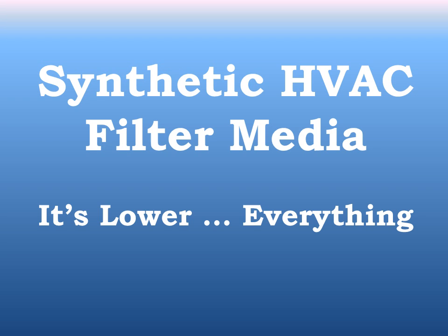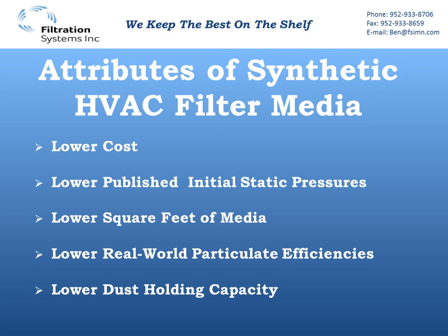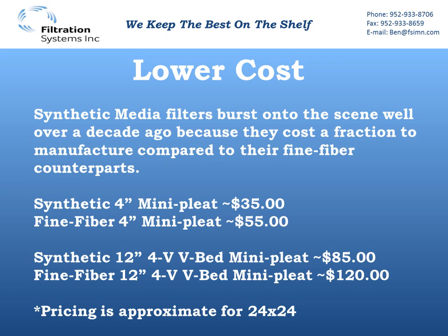Synthetic HVAC filter media. It's lower. Everything about it is lower. So the specific attributes of synthetic HVAC filter media are lower cost, lower initial statics, lower square feet of media within the filters, lower real-world particulate efficiencies, and all of that ends up with a lower dust holding capacity.